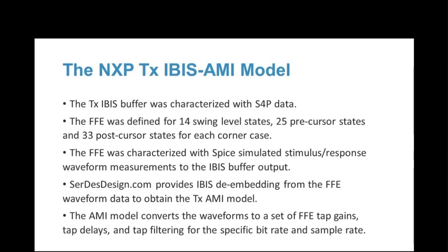The IBIS-AMI modeling approach was based on collecting SPICE circuit simulation stimulus response waveforms for a defined set of the FFE states. The response waveforms were at the IBIS buffer output. The IBIS buffer characteristic had to be de-embedded from the FFE response waveforms to obtain the FFE-AMI model characteristics. Thus, the combined IBIS buffer model and AMI model provided the same characteristics as defined by the transmitter stimulus response waveform data.